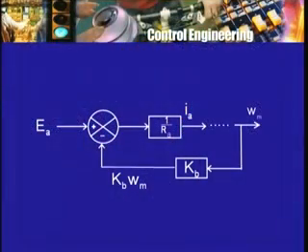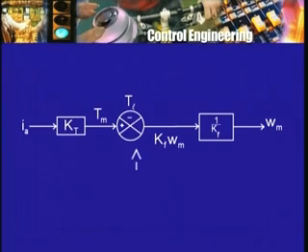In the case of the signal flow graph, each node other than the input node represents an equation or a summation. Here this circle device, which in this case we are interpreting as a difference device, represents an equation, and there are two of them, one for the armature circuit equation and the other for the torque equation. So putting these two equations or the two blocks together, I will draw the composite diagram, and you should try to draw it by yourself now without looking at what I am drawing, by going through the thinking once again. So how do we start?